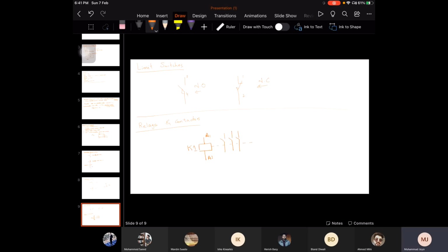All the relays and contactors used in electro-pneumatics need to be represented with K. The term K defines the relay. So if there are three contactors, you will name them K1, K2, and K3, right? K will represent the controlling part, that means the contactor or the relay. And the output switches over here, these three switches, will be used to drive any output.